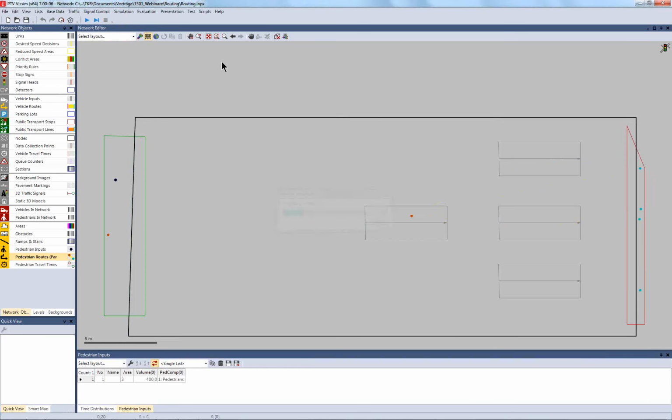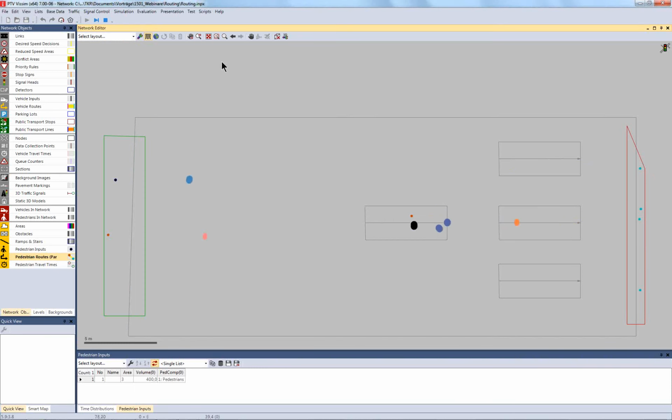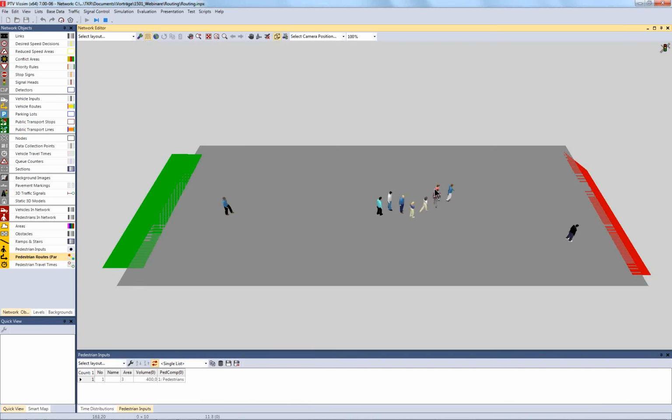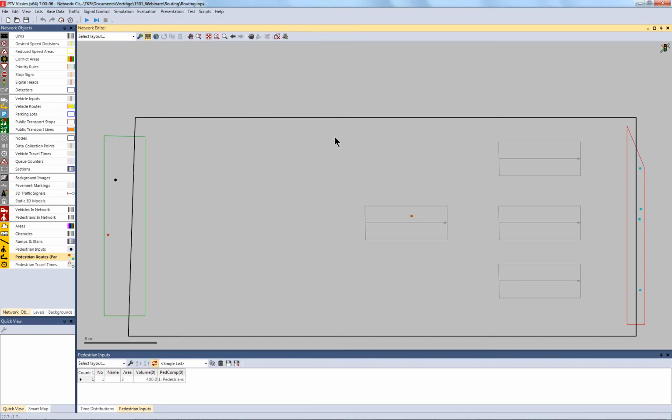And we see the following. Still now the pedestrians have a long reaction time here, the 20 plus minus 2 seconds, they are still applied, which is not really realistic. Sometimes it might be realistic to have some reaction time, so that they're not proceeding immediately. So you can have a time distribution of 1 or 2 seconds or something like that, but 20 might be just too long.